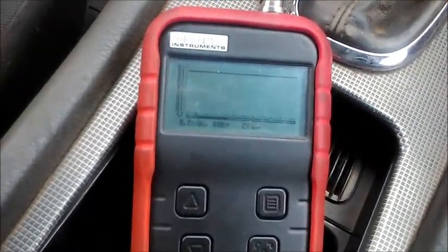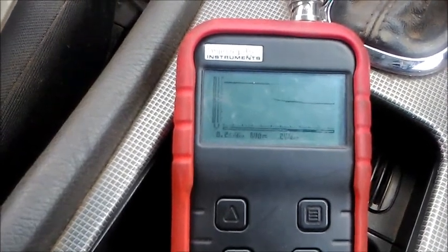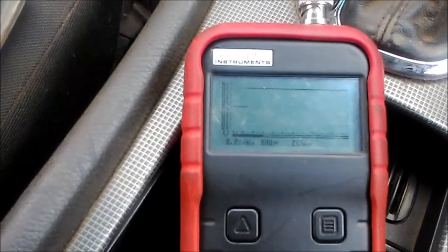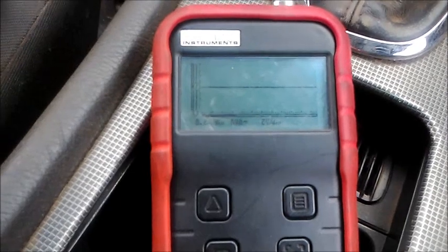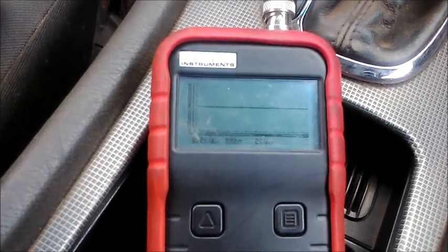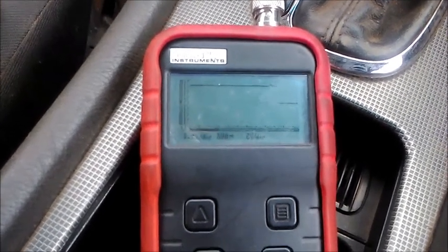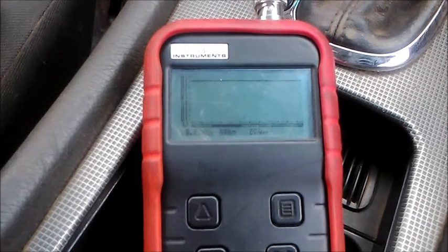And I'm going to turn the key off so you can see the signal go low when the computer goes dead. See, the signal has just gone low because the computer is now dead. I'm turning the key in the ignition switch on again. Signal goes high again and it stays high.